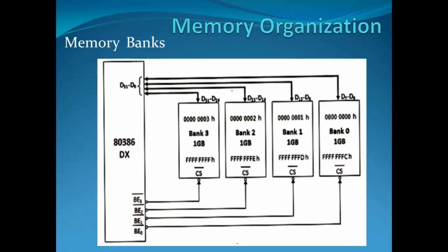The 8088 requires 4 memory cycles to accomplish the same transfer of 32-bit wide numbers, whereas 286 and 386 require 2 cycles. Today, data is more important, especially single precision floating point numbers that are 32-bit wide. High-level software normally uses floating point numbers for data storage, so a 32-bit memory location speeds the execution of high-level software written to take advantage of this wider memory.